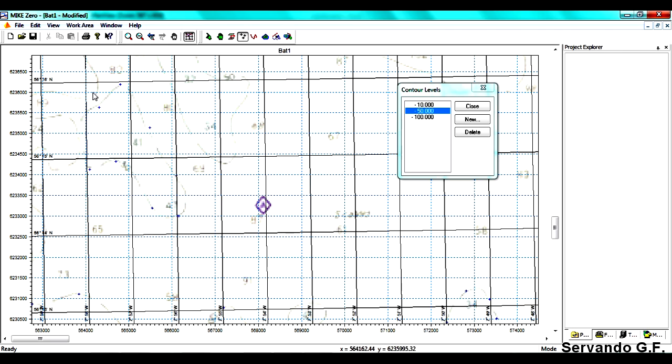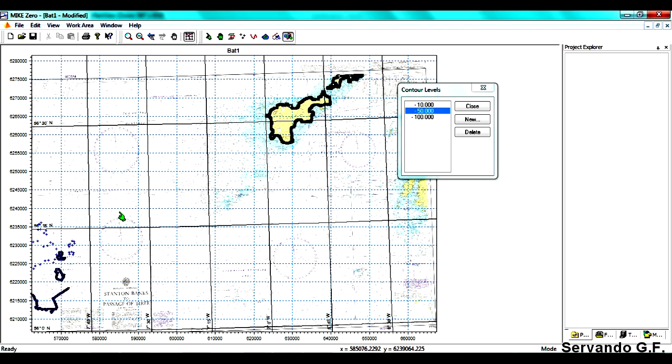If you have made a mistake while defining those points, what you can do is to move those points. See, you're just clicking on the point, and you can move it around to fit the bathymetry if you think that this is not accurate enough. This other little green hand here is just to select points. If you need to delete one, just select the point, click on delete, or press the delete button, and it will delete the line. And that's it. This is digitizing the Admiralty chart.